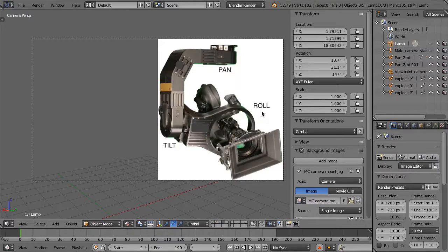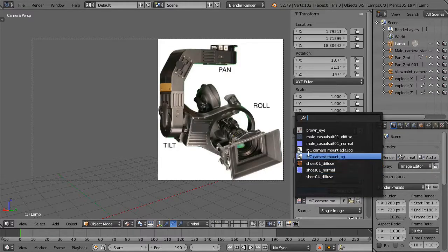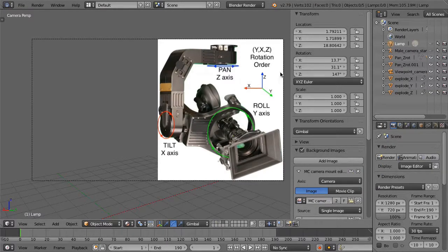The three rotation axes are configured with the pan or sideways rotation on the top and outside of the order. Attached to the pan axis is the tilt or up and down rotation. Then last, the roll axis is attached to the tilt axis and rotates the camera around the optical axis of the lens. In Blender, this rotation order is specified as YXZ.